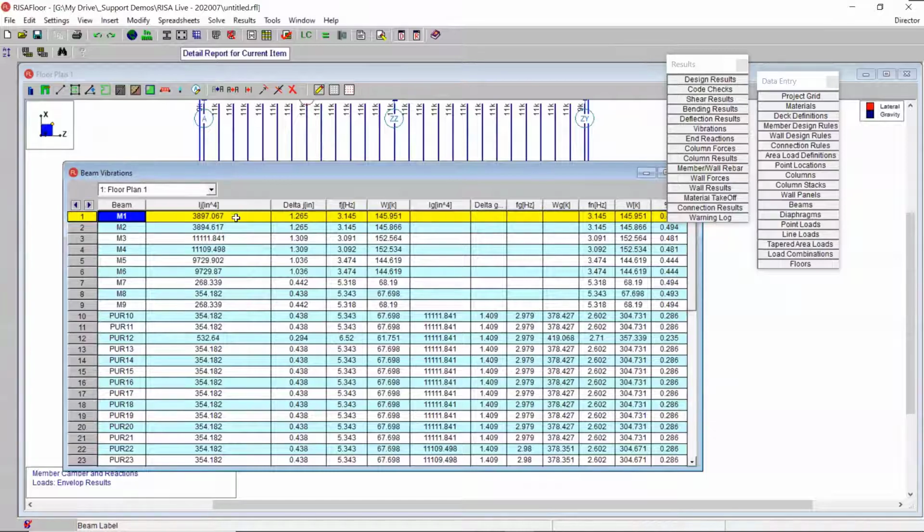The moment of inertia will also contribute to the calculation of the mid-span deflection of the joist under the vibration loads. The program then calculates the natural frequency of the joist for vibration and also the effective panel weight of the joist areas.